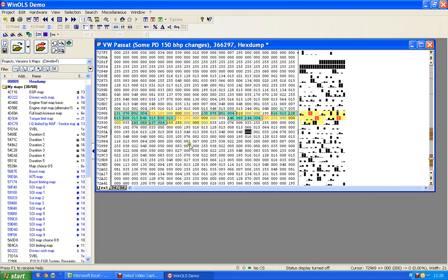Okay, now if we've got this now correct, then I've still got all my faults in there, so the fault codes are in there. They will just never occur in terms of being counted up to, and if by some miracle they did occur, they would be instantly healed. And if they are driven by an individual event counter that may be every time I turn the ignition on and then turn it off again, I've set that to 0 as well, so it's counting from 0 to 0, so they should never occur either. And so with a little bit of luck, having done that, I should never get any EGR errors.